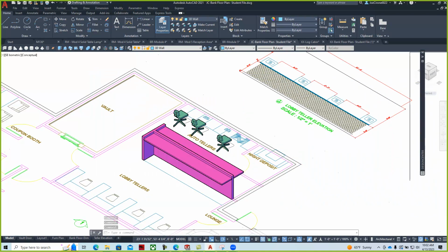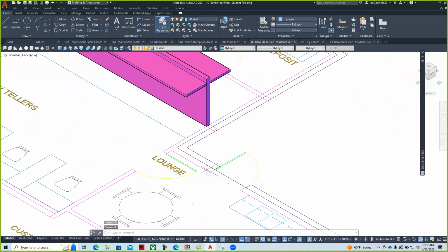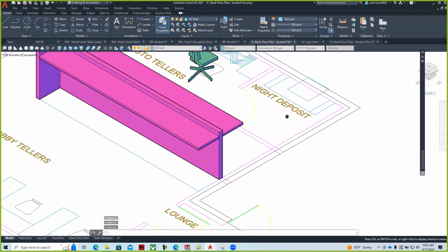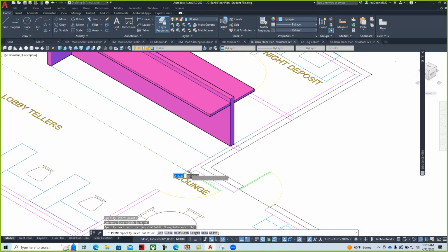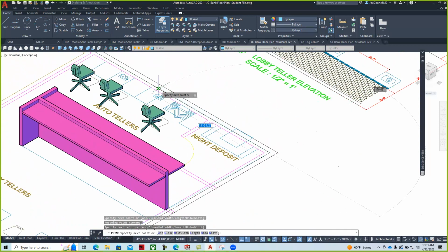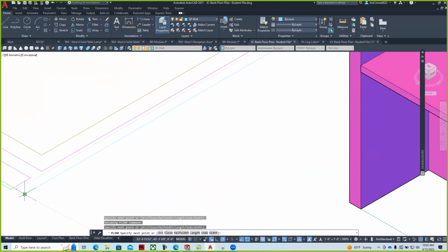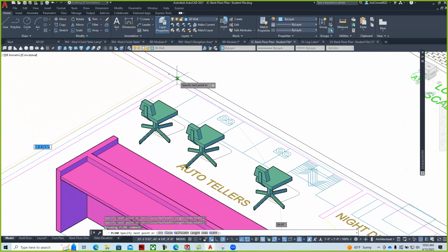Pull this to my second screen. And just like we were doing before, it's not a bad idea to polyline around the building walls to be able to bring that up. And so we can polyline over our existing geometry on our 3D wall layer to create a boundary shape for that. And so it doesn't have to have the whole wall. We can do Boolean activities to join them together after we've created them. So I'm just going to go like this.